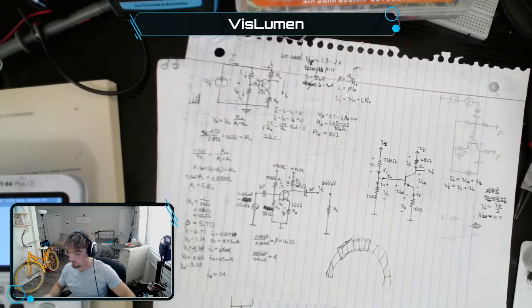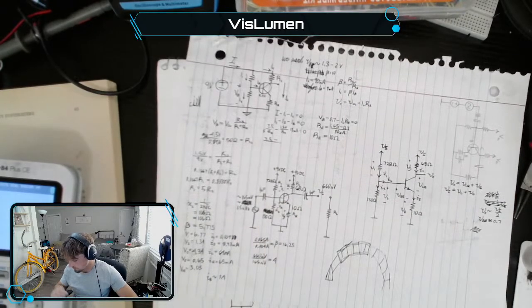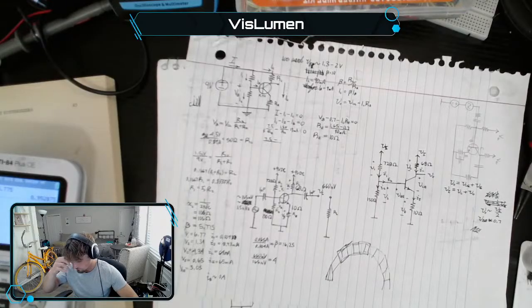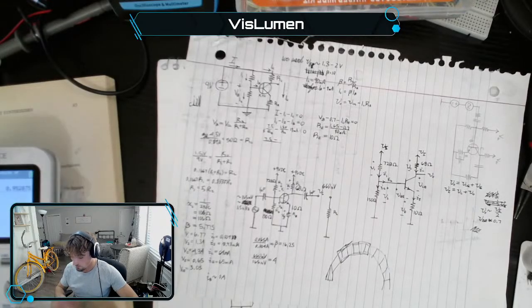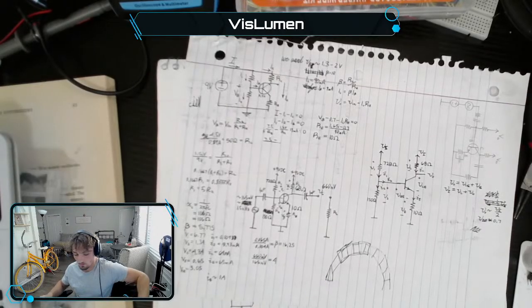The DC doesn't get past that, so it would matter. And I was applying 165 millivolts. Can't believe I didn't write it down, but the output, the signal output. 165 times 5.775. Okay, so it's approaching one volt, 0.953. We'll round it.